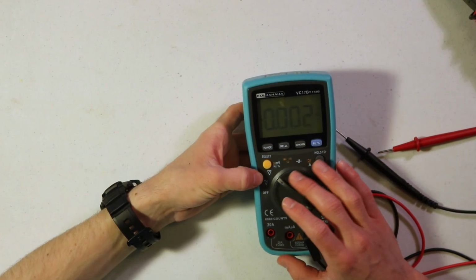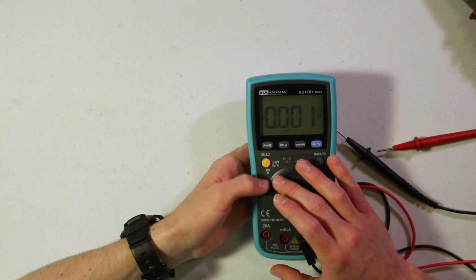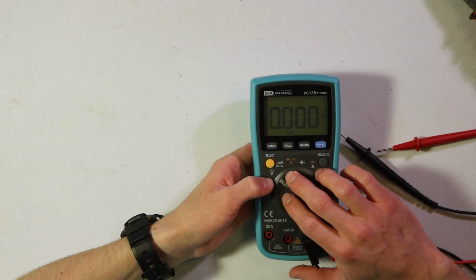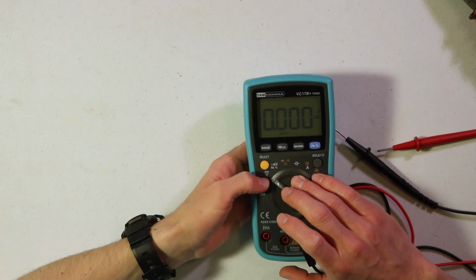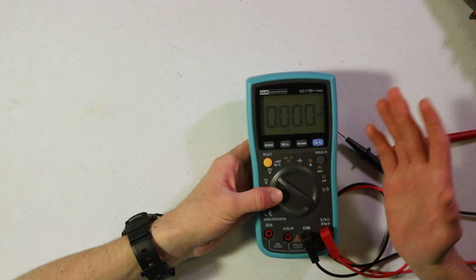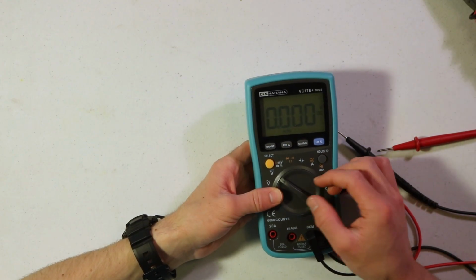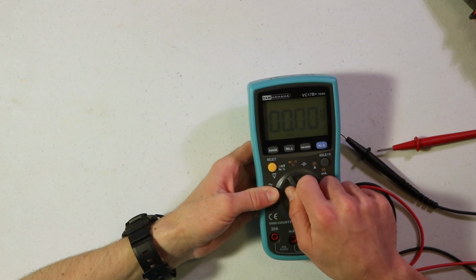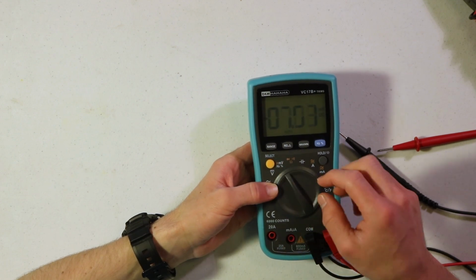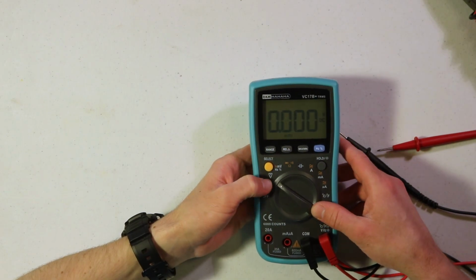For the one I have here, it looks like it's mostly auto ranging, although there are two categories here for voltage. We've either got just regular volts, or we've got millivolts. And millivolts, that's just 1,000 times less than a volt. So if I'm going to be measuring very small voltages, then I would want to set it to the millivolt rating. And if I want to measure larger voltages, then I would set it to the volt rating.